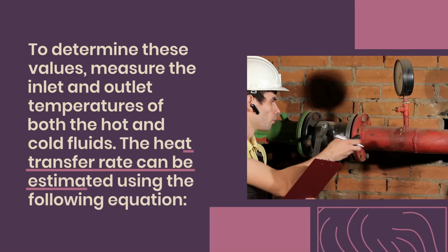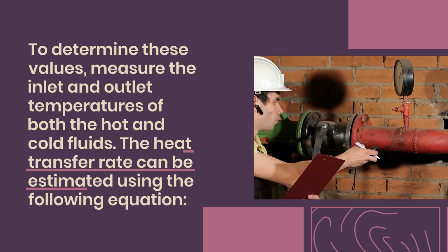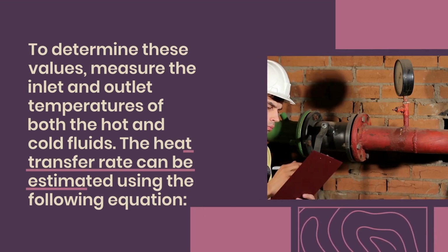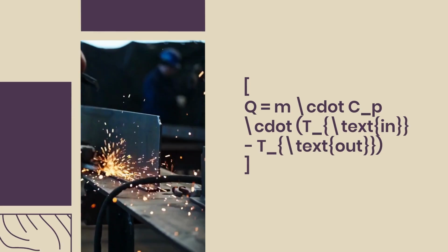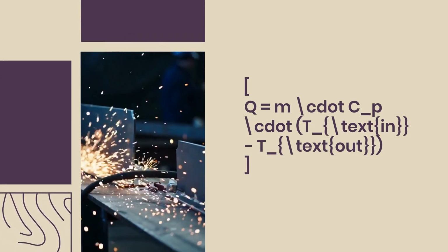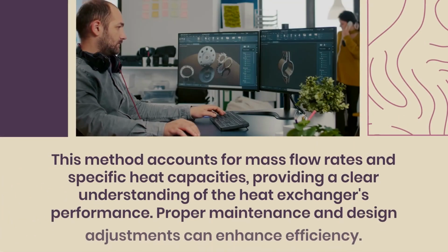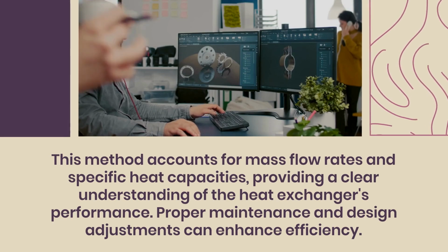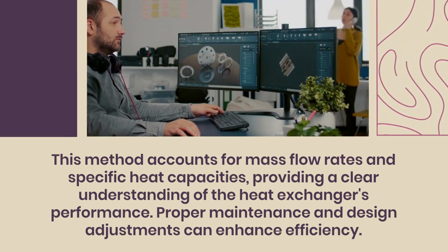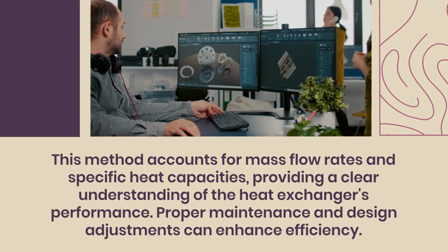To determine these values, measure the inlet and outlet temperatures of both the hot and cold fluids. The heat transfer rate can be estimated using the following equation: Q = m · c_p · (T_in - T_out). This method accounts for mass flow rates and specific heat capacities, providing a clear understanding of the heat exchanger's performance. Proper maintenance and design adjustments can enhance efficiency.